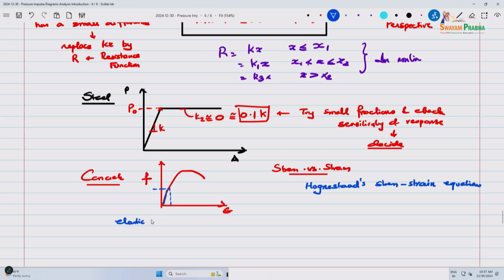Now, given that, you'll see there is a little bit of anomaly when we do design. The elastic response is F less than 1/2. The term F, it's FCK here, right? We use the term FC prime, and you might see me use FC prime by 2. That's the same thing. Up to that stress, you can calculate your stiffness, basically the slope from that expression.